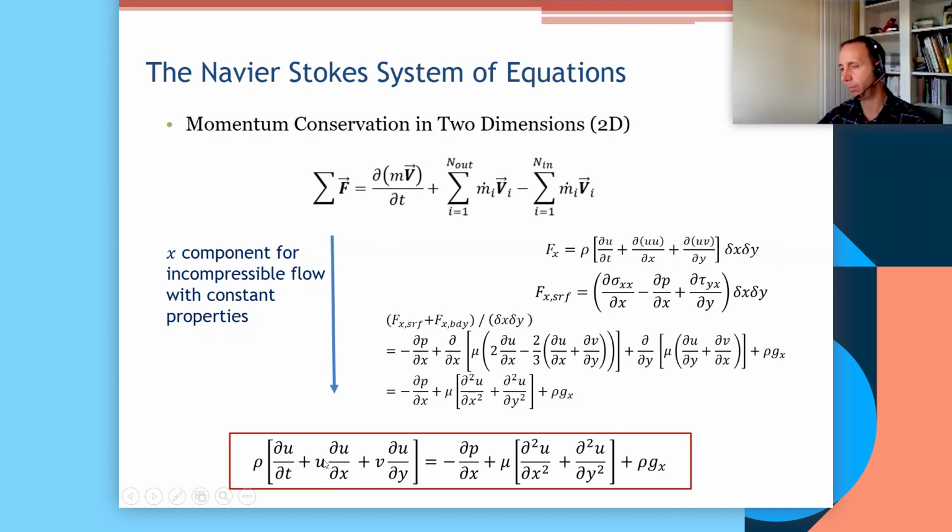You can repeat the same for the y momentum conservation equation, which is not done on the slides, but it's done in the lecture notes. The combination of the x and y momentum conservation equations plus the continuity equation defines the governing equations of fluid mechanics, where we don't account for temperature effects and we only look at a two-dimensional representation. You could do the same for three dimensions. There's nothing fundamentally different in the derivation of the equations. And that concludes the derivation of continuity and momentum, which are the governing equations for fluid mechanics.